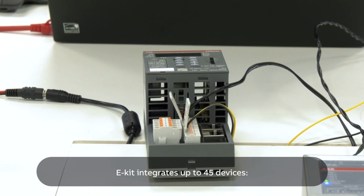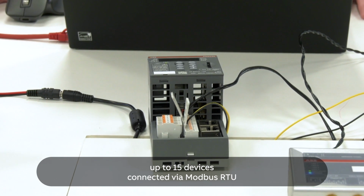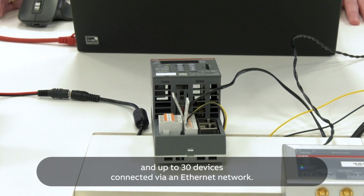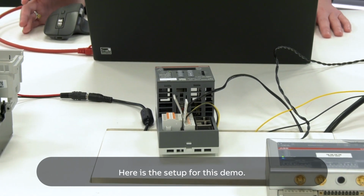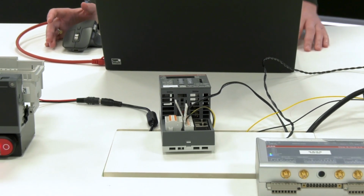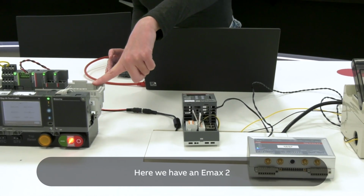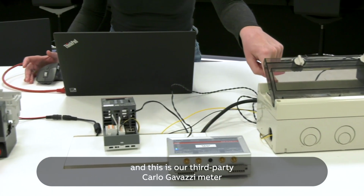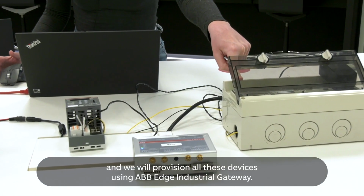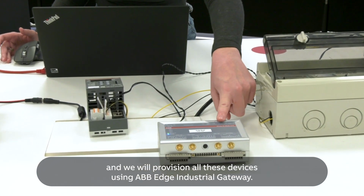E-kit integrates up to 45 devices, up to 15 devices connected via Modbus RTU, and up to 30 devices connected via Ethernet network. Here is the setup for this demo. Here is the E-kit. Here we have an Emax2, and this is a third-party meter, Carlo Gavazzi, and we will provision all these devices using ABB Edge Industrial Gateway.